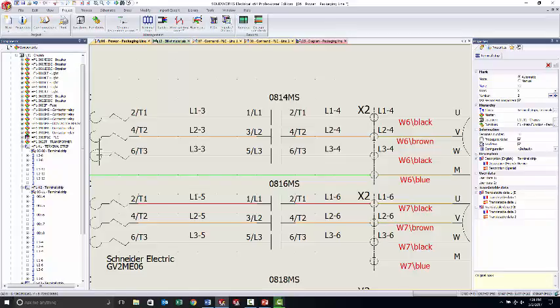So if you're creating a new location, this is a way you can get around creating those detailed views. Maybe you're drawing in a 1-to-1 scale and you want a view of a smaller portion of your cabinet. Remember I said the locations are subassemblies. You could create under this chassis just the terminal strip as a location.